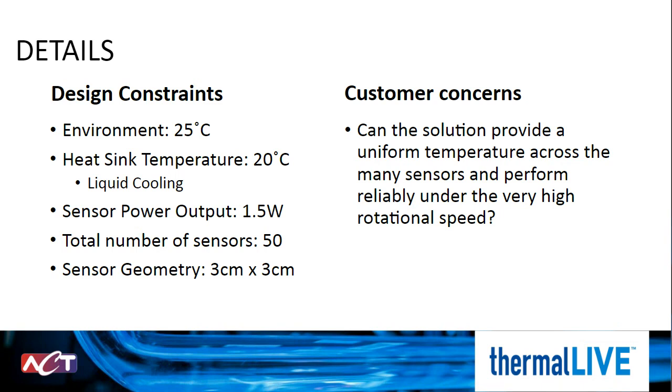The customer's main concerns are, can the solution provide a uniform temperature across that many sensors while also operating in a rotational speed? This is also very important because we need to look at the effects of acceleration on our thermal solution. Are we going to have acceleration forces on any liquid that we're going to apply to this?